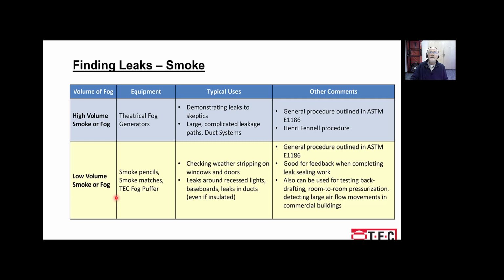We're going to show a little video. Even though there's insulation and a lot of stuff in the way so that you can't see very well, when you squirt smoke you can see the fog very easily going into where the leaks are. With the house depressurized to about 30 pascals, we can see lots of leaks. Now, oh boy, we find a duct, a supply duct, that's leaking.